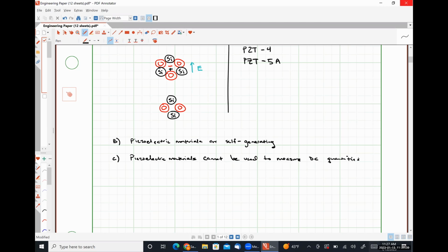So if we had an accelerometer, a cantilever beam that had a piezoelectric sensor to measure the strain, when we depress our cantilever, that change is going to give us some signal, but the continued application of that force is not going to continue to generate a signal. So we're going to see a transient effectively.